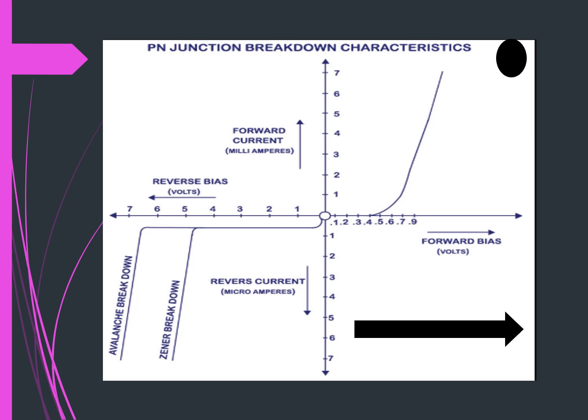But for the reverse current, when you're plotting reverse bias versus reverse current, the unit for the reverse current will be in microamperes, because in reverse the current is due to the minority carrier, whereas the forward current was due to the majority carrier. So if forward is in milliampere, the reverse one we are getting in microampere. Next is that the same phenomenon does occur like this.